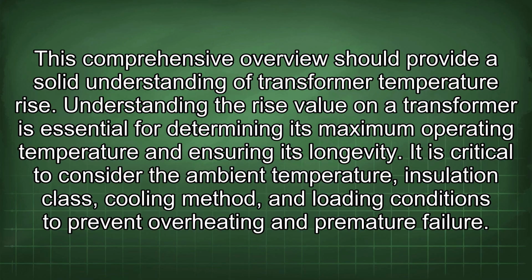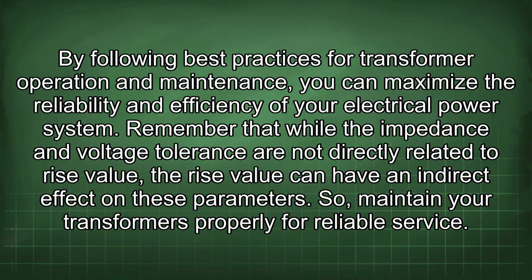Understanding the rise value on a transformer is essential for determining its maximum operating temperature and ensuring its longevity. It is critical to consider the ambient temperature, insulation class, cooling method, and loading conditions to prevent overheating and premature failure. By following best practices for transformer operation and maintenance, you can maximize the reliability and efficiency of your electrical power system. Remember that while the impedance and voltage tolerance are not directly related to rise value, the rise value can have an indirect effect on these parameters. So, maintain your transformers properly for reliable service.